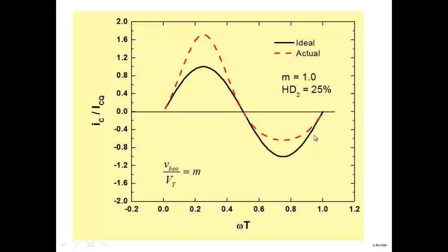Now can you see why my swing in the positive direction was less than the swing in the negative direction? You see this current: when current increases, note that the voltage decreases in your amplifier. As collector current increases, the voltage decreases. So positive swing in the collector current translates into negative swing in the voltage, and negative swing in the collector current translates into positive swing in the voltage here. Because voltage is nothing but VCC minus IC times RC here. So that's where the negative part comes.